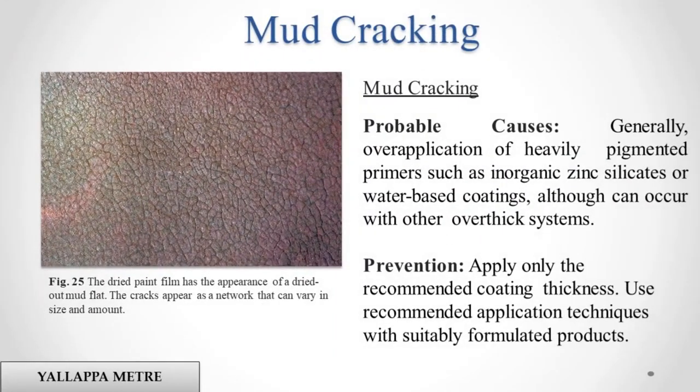Mud cracking. Probable causes. Generally, over-application of heavily pigmented primers such as inorganic zinc silicates or water-based coatings, although can occur with other over-thick systems. Prevention. Apply only the recommended coating thickness. Use recommended application techniques with suitably formulated products.